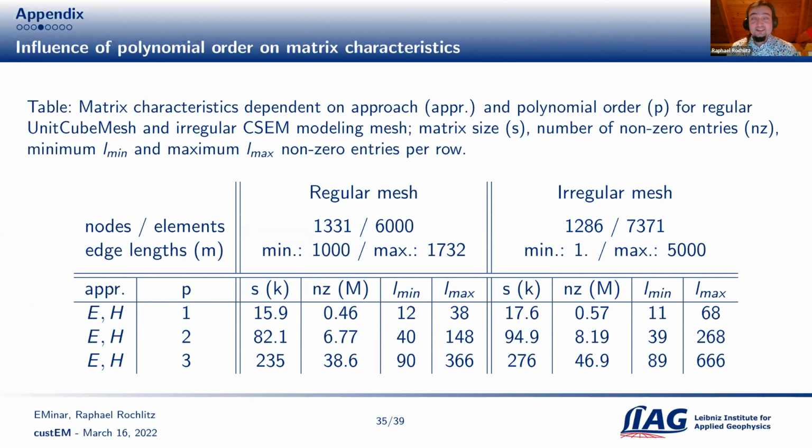And there's another reason. And this is also a point that P1 is not completely useless. It is definitely not, because if our model geometry is so complex that we need many, many cells, we are not able to handle this with P2. So if our geometry requires many tetrahedra or many cells, we need to stay with P1 clearly. But if we have a geometry which allows us to go for P2, I would say this is the optimum compromise, and P3 is overkill, and this is also what Octavio and Alexander have written in their publications.